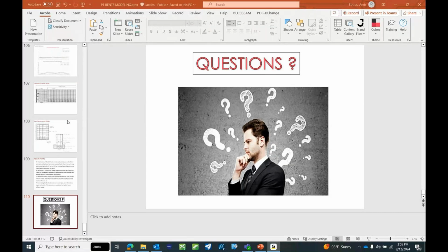So we are not quantifying it or inputting anything. We are just defining the appropriate material properties and what we think are reasonable durations for each construction stage, and we just run the analysis, look at the effects from creep and shrinkage on the members, the secondary effects, of course, on the columns, on the foundations.